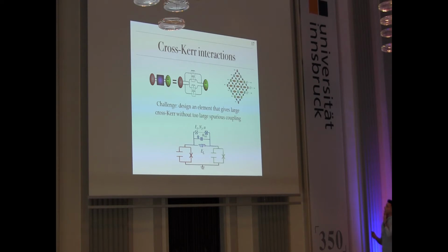Okay, so ideally, however, we would like to completely cancel the hopping from here to here, and that would also guarantee that we have somehow a small interaction between qubits on the same line. In order to do this, we came up with this coupler that is formed by essentially an inductance, a Josephson junction, and an array of a few junctions, 4 in particular.